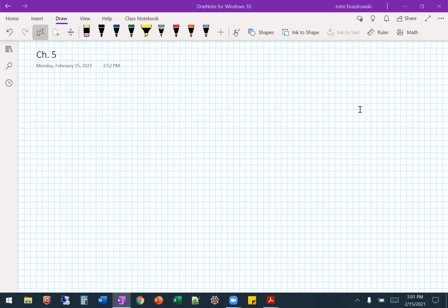All right, we have a couple examples from chapter 5 to do first. So we'll start with 5.15. Carbon steel, AISI 1010, shaft of 0.1 meter diameter, heat treated in a gas-fired furnace whose gases are at 1200 Kelvin and provide a convection coefficient of 100 watts per meter squared Kelvin. If the shafts enter the furnace at 300 Kelvin, how long must they remain in the furnace to achieve a centerline temperature of 800 Kelvin?